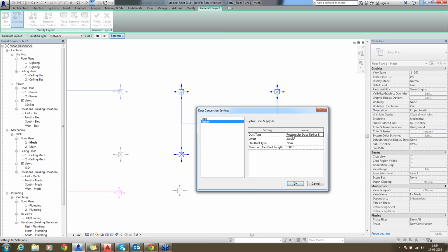We take the branch duct. I'm going to take a round duct tap. See, here we have the tap and T. I will explain clearly once again about the tap and T. I'm just taking a round duct. Here, the maximum length of the flex duct, yesterday we discussed, should be less than 1 meter. It's the most economical thing.